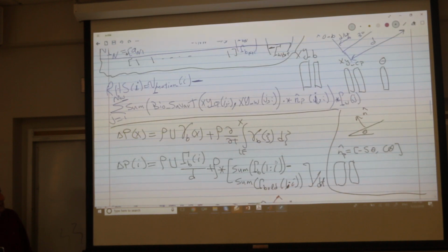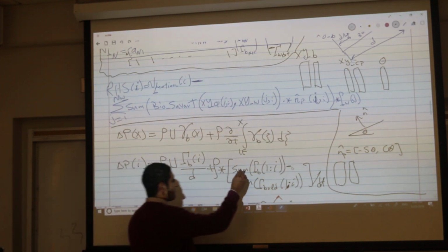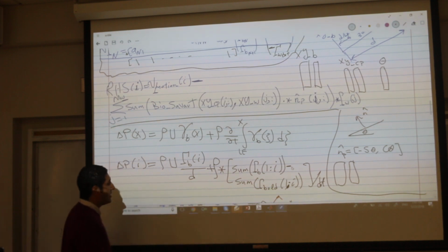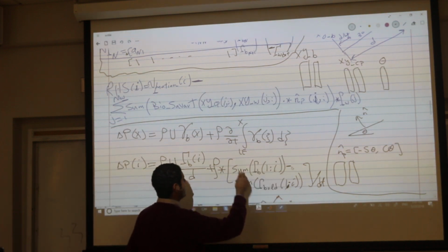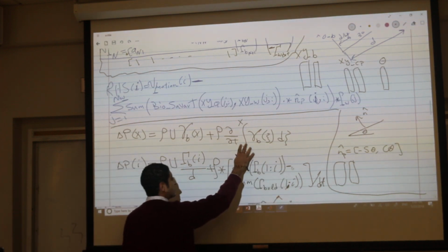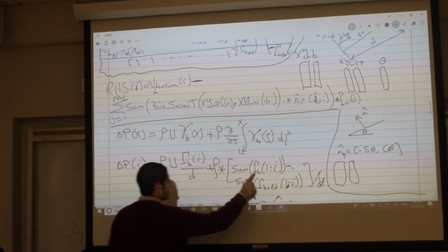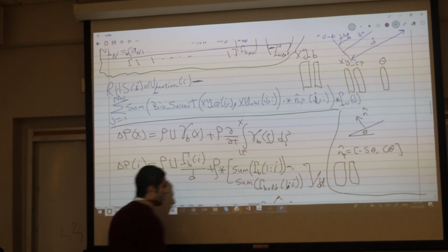We will do it like any numerical technique, the simplest thing, which is forward difference. So whatever I have now minus whatever the last time, divided by delta t. And what is the quantity that I need to do that? It's this integral. So it's the summation of all gammas up to your x, up to your panel, the summation of all gammas up to my panel I.